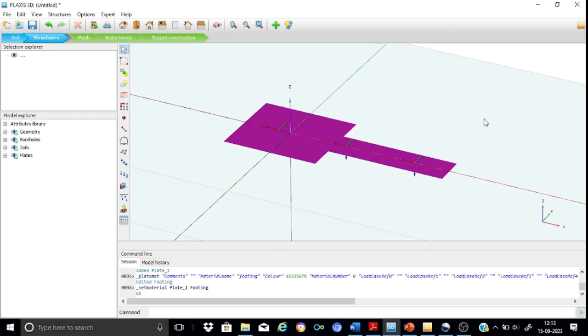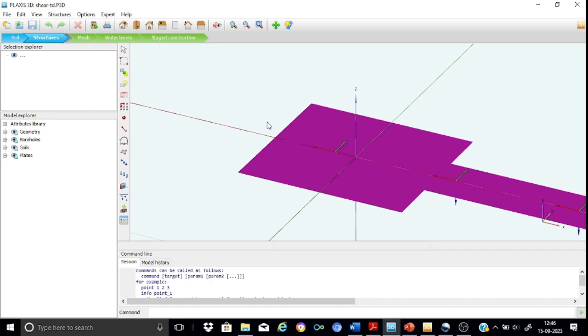So having defined and assigned properties for the mat foundation, now we shall proceed to create the shear wall, and the shear wall will be created from 0 meters up to an elevation of 3.0. Okay, fine. So let us first draw the four lines that represent the footprint of this shear wall on the foundation. So we can just straight away create the lines.